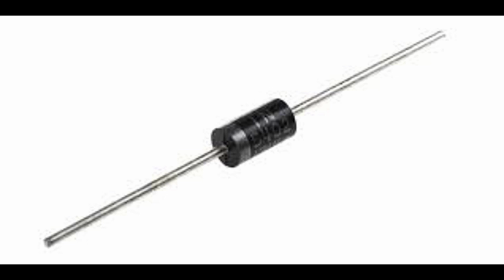Circuit configuration: in a voltage clipping circuit, diodes are placed in parallel with the signal path. The diodes are oriented in such a way that they are forward biased when the input signal exceeds a certain voltage threshold. Diode operation: when the amplitude of the input signal rises above the diode's forward voltage, also known as the diode's turn-on voltage, the diode begins to conduct and allows current to flow.